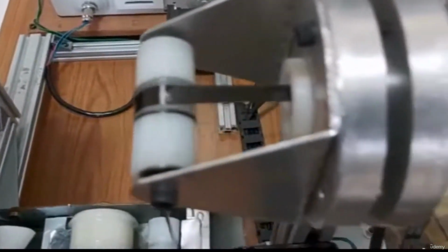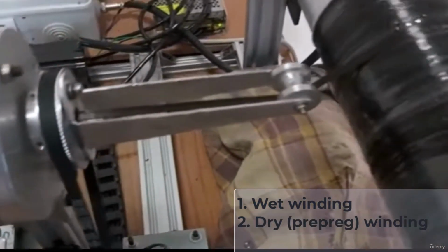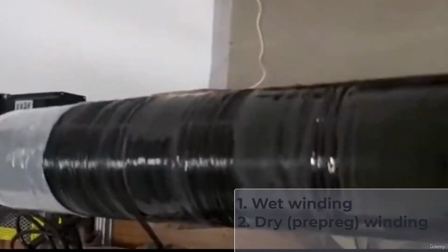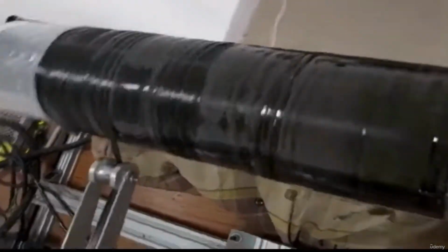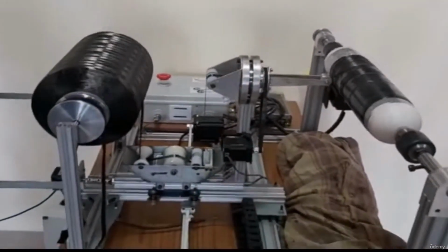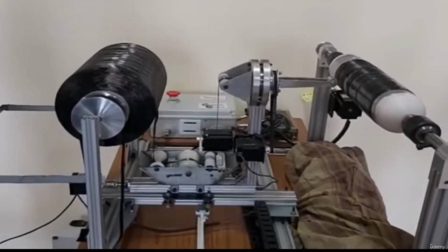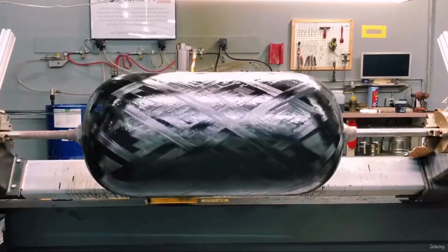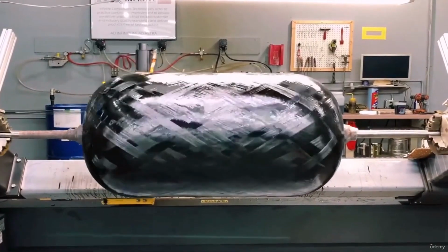One is called wet winding and the other one is dry winding. In wet winding, the fibers are unwound from a roving and pass through a bath of resin mixture for impregnation before being wound on a mandrel in a defined orientation. The pattern of placement is controlled by the rate of rotation of the mandrel and the feeding or metering mechanism, creating a 3D